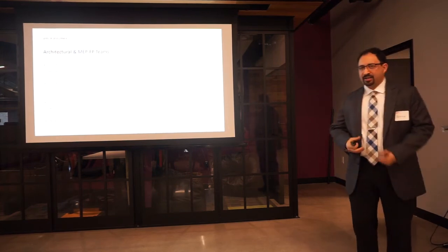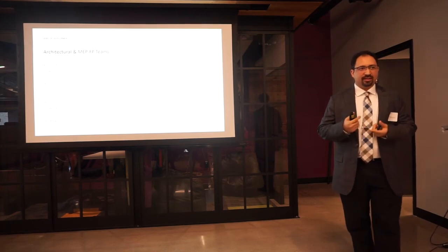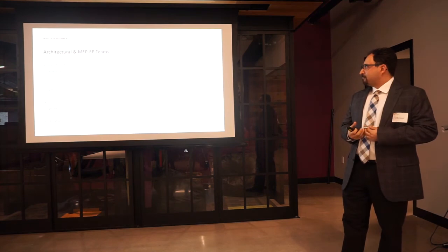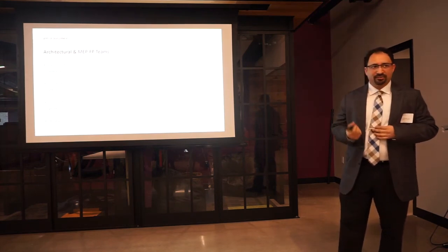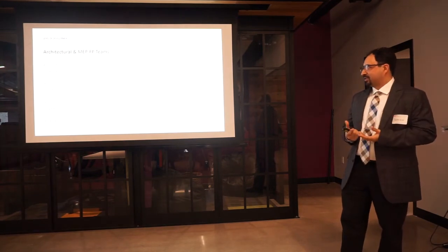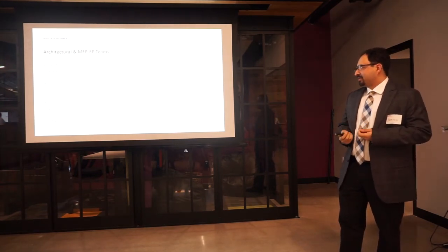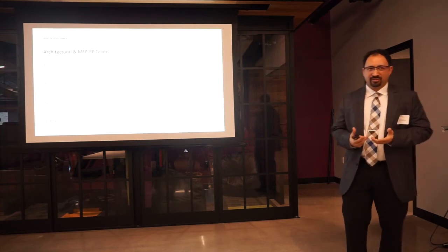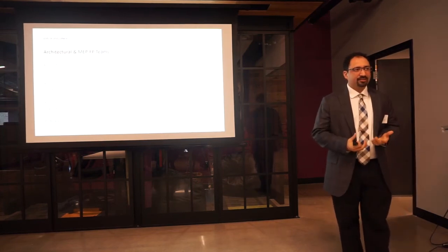So we set in the execution plan the requirements for each firm's development. We developed level 100 as our standard schematic design. Level 200 was our design development, where we had our approximation of location of items. 300 was our 100% construction documents.